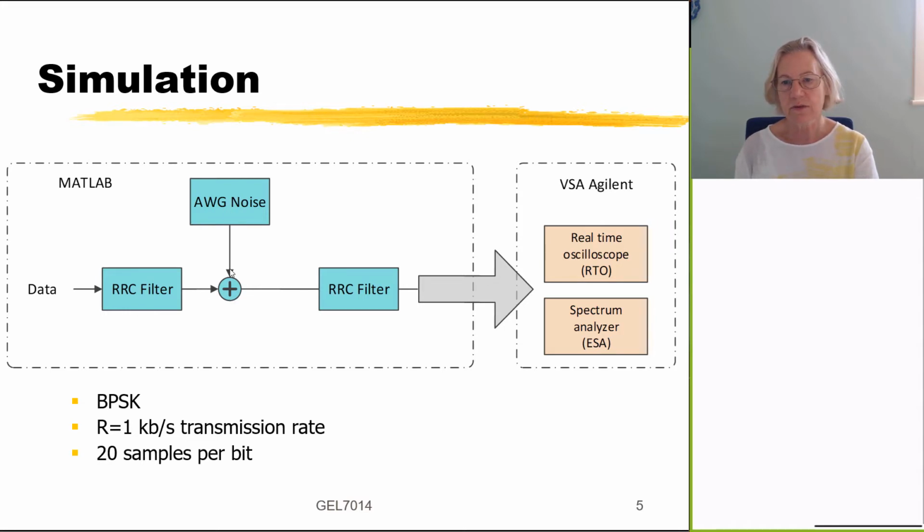And here at the receiver, of course, I would use a matched filter receiver, so I would have another filter, which is identical, another root raised cosine filter. Then I would have the received signal here, which would be inside of my linear sampling receiver.